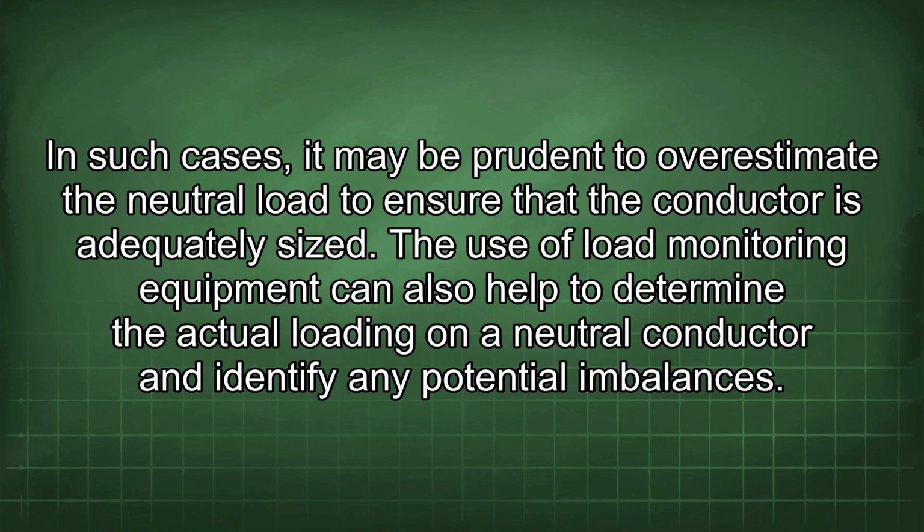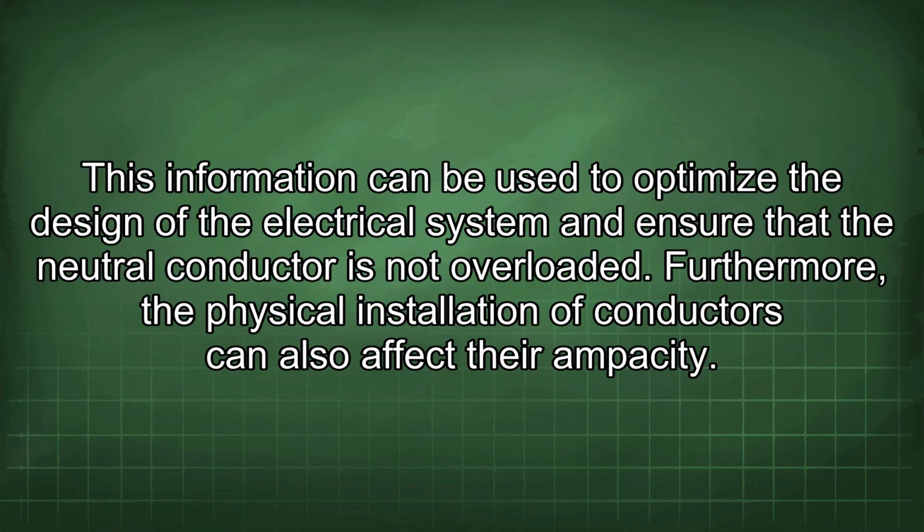The use of load monitoring equipment can also help to determine the actual loading on a neutral conductor and identify any potential imbalances. This information can be used to optimize the design of the electrical system and ensure that the neutral conductor is not overloaded.